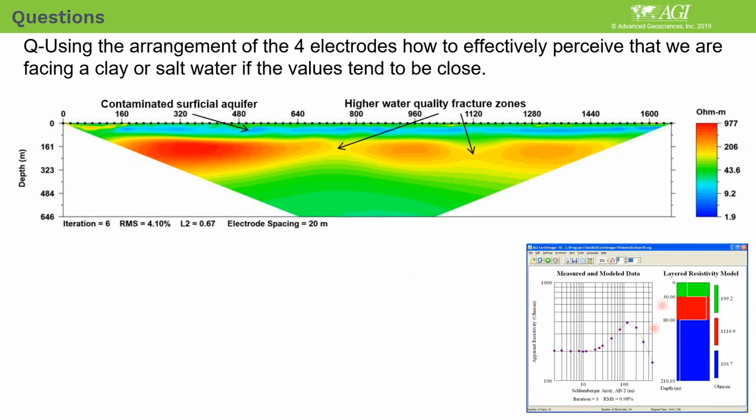So that means if I do 1D, I just get that section of the resistivity values, nothing else. If your vertical sounding is located here, you get just 2 layers. The top is the salty water, and then limestone, dry zone. So that shows how important it is to do 2D multi-electrode measurement over here. You really need to know where to drill, and how deep you need to drill is also important. So this example really gives you that.